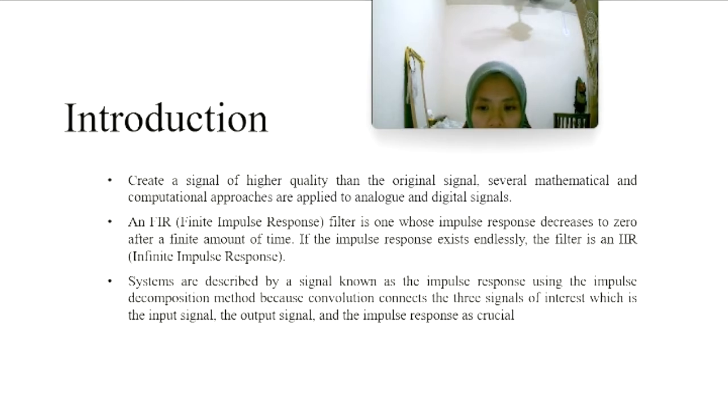Infinite impulse response is a form of digital filter. The function of a filter is to allow certain types of signal to pass while blocking others. The infinite impulse response filter is distinct in that it employs a feedback mechanism. So an FIR, finite impulse response filter, is one whose impulse response returns to zero after a finite amount of time. If the impulse response exists endlessly, the filter is an IIR, infinite impulse response.